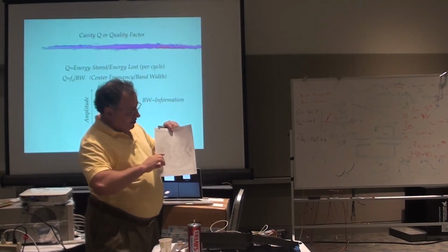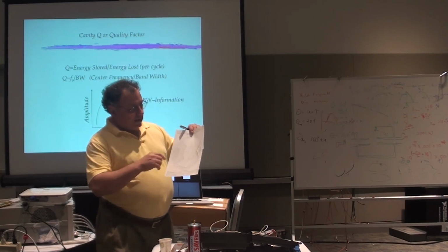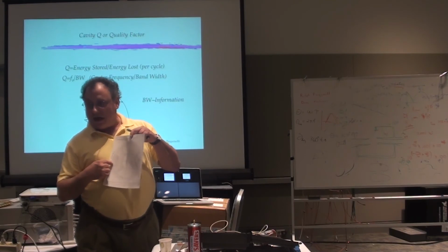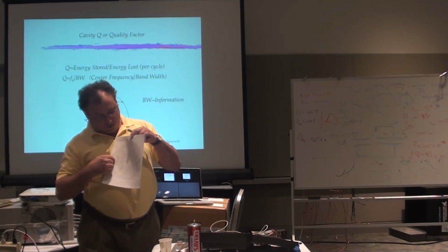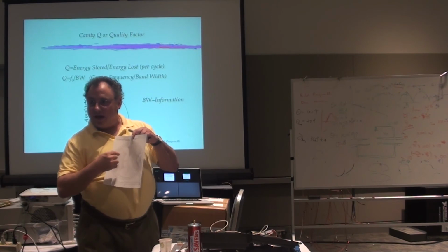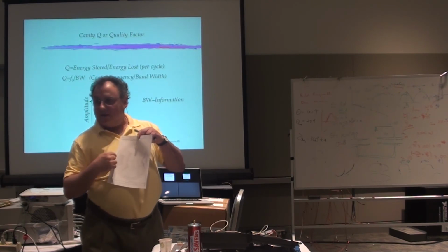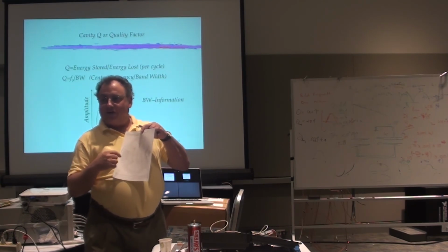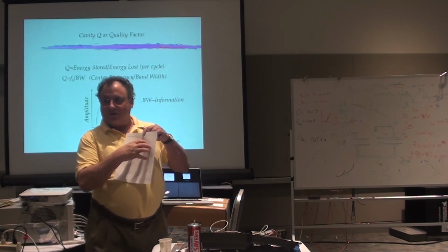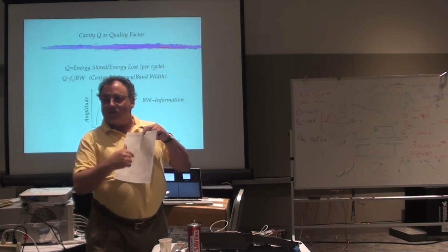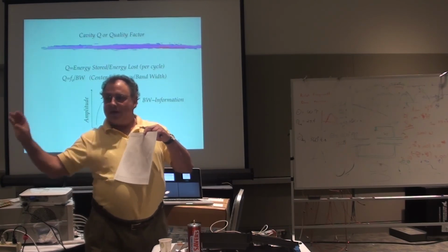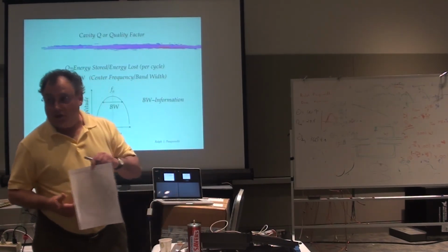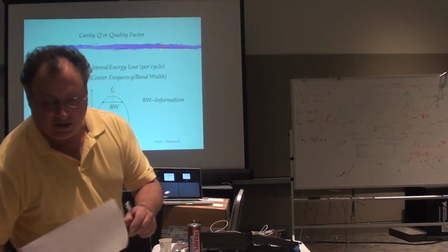and that's what multiple elements do. And you can actually draw, and I would encourage you to do that, by just looking at the real and imaginary parts of points on here, lines of constant Q, where there's a Q essentially of 1 on the real axis and a Q of infinity on the outside, and you can draw Qs of 1 and 10 and something like that. And if you're making your matching network, even though you know eventually you want to get to the unit circle, what you've got to do is maybe get there in several steps and don't exceed your Q bandwidth. You're going to end up with a wider bandwidth matching network. And that's what you have to do if you have the need for wideband systems.